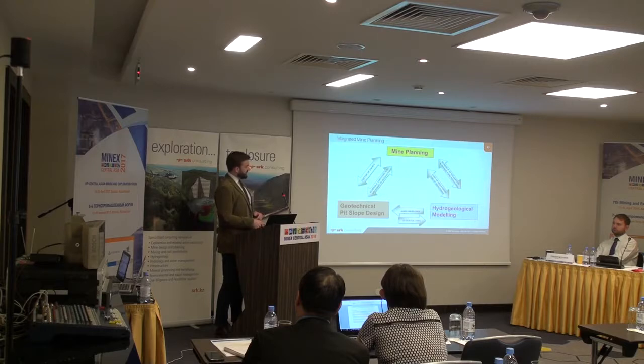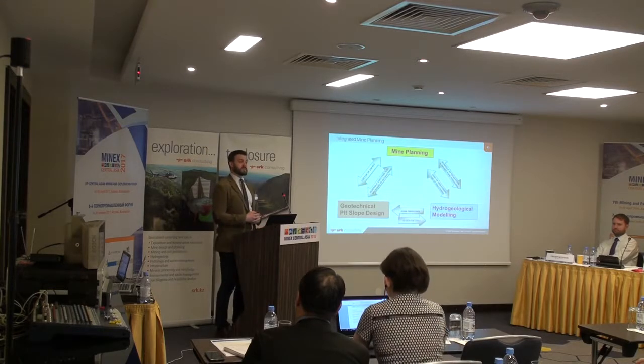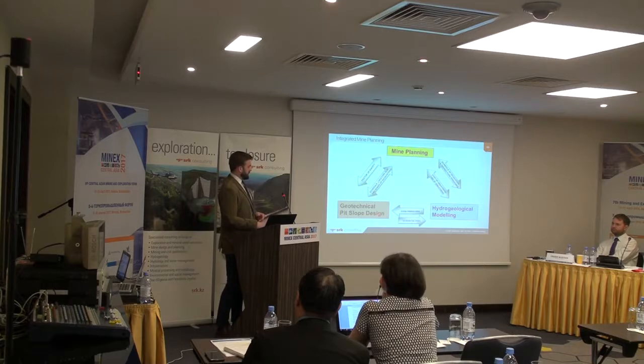Then what we get from the hydrogeological modelling is pore pressures, and specifically in weaker rock masses this can be very critical to any pit slope design. And then we give design factors to the hydrogeological modelling.